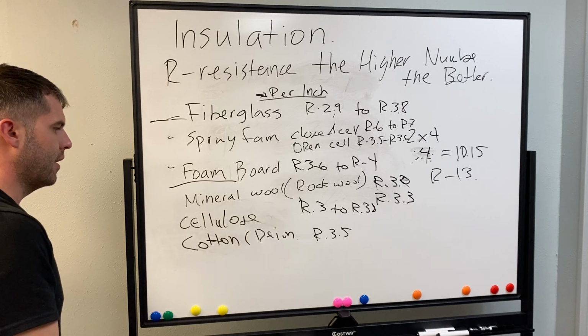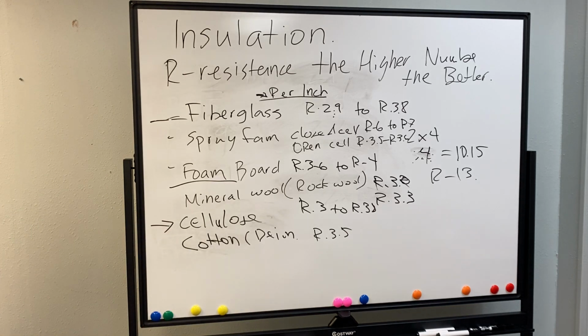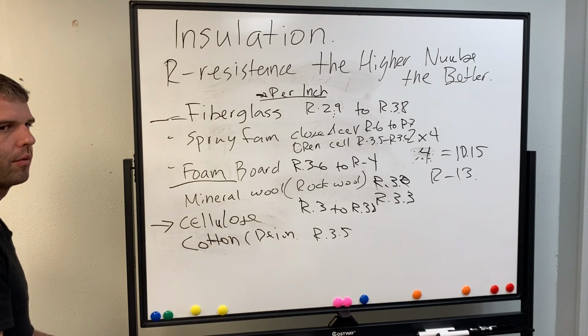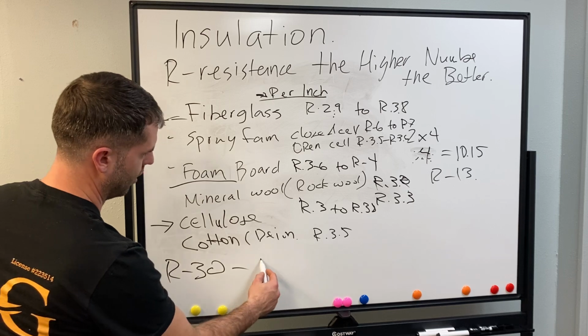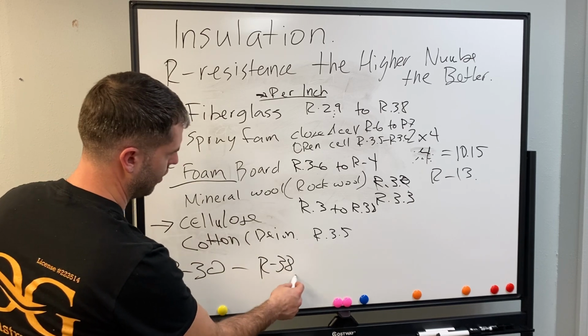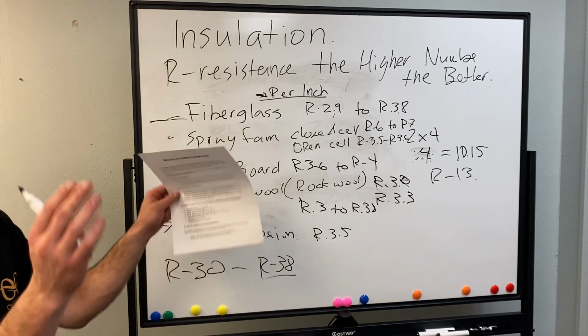When you get to an attic space, it's very recommended to not just put batts, because the maximum you can get on a batt or a rolled out insulation is R30, right? And I think R38 is the maximum that it goes to for a batt or a roll or something that's together.